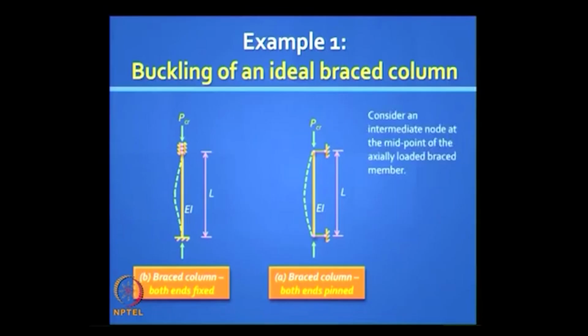Well, you just need, we will try this out, okay, we will just put one node in the middle. You can divide into 3 elements, you will get a better result, 4 elements even a much better result, but let us check out with just 2 elements whether we get a reasonably good result or not, and that will validate our method. So we will do that, and we will write the stiffness matrix, and we will put the determinant equal to 0 for the active degrees of freedom.